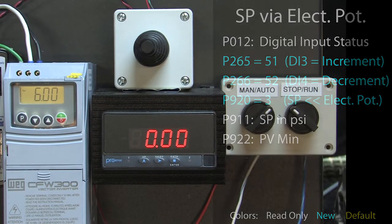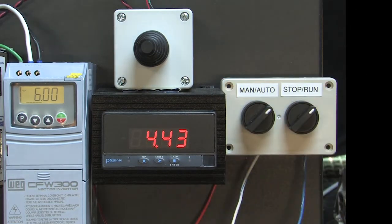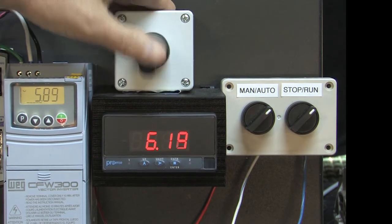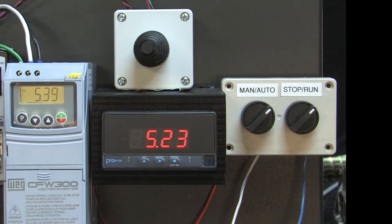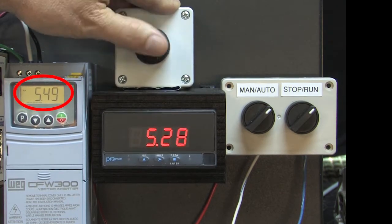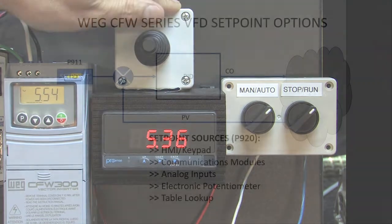Looks like everything's working, so let's switch to run, and the PID application automatically adjusts the motor speed to get us to 6 psi. And of course I can change the set point using the joystick to increment or decrement the electronic potentiometer. And again, if I just toggle the joystick, the set point just increments 1 digit at a time.